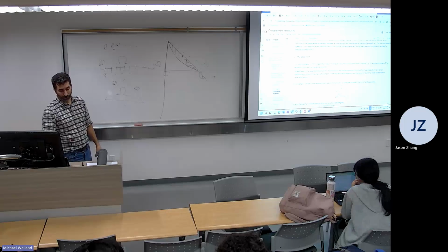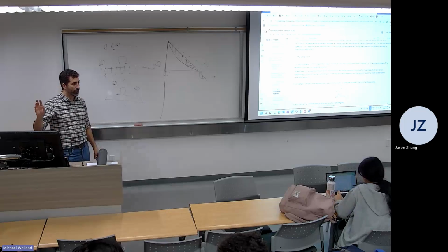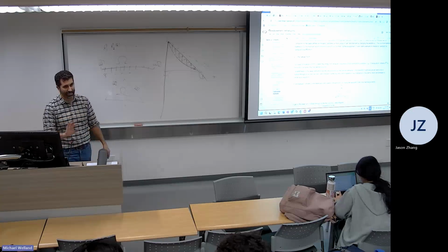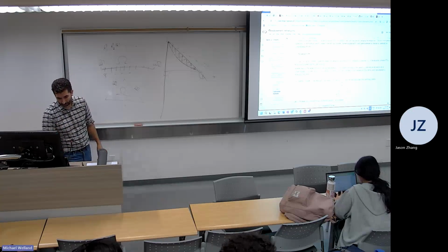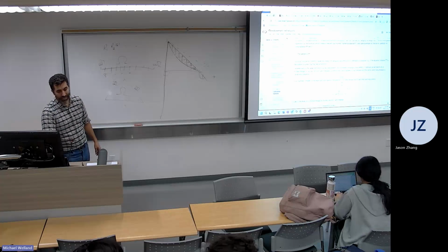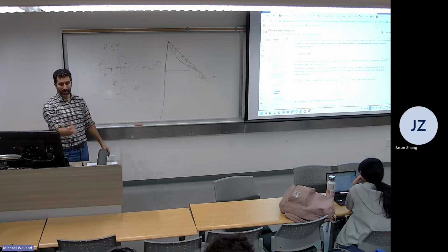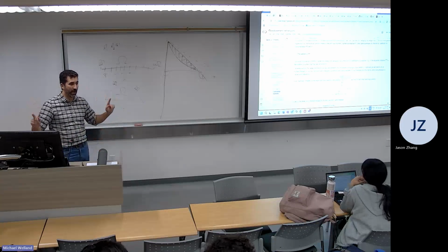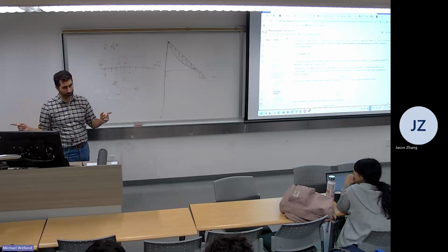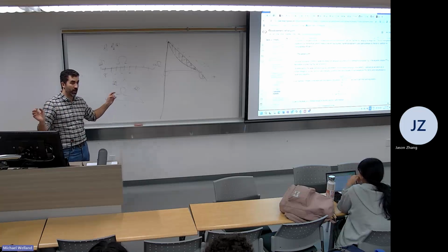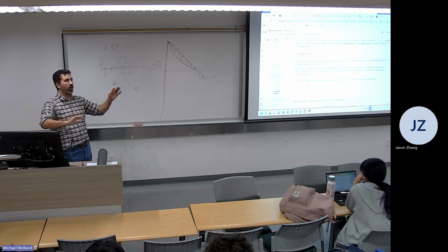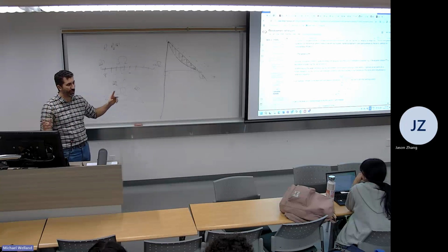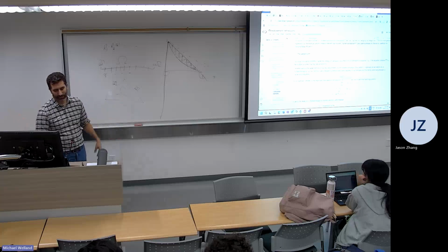MWR leads to the weak form because we're introducing this test function, but we can also just introduce the test function and manipulate things around, and we don't have a problem with it. What we have to do is we take our strong form, we multiply it through by this test function, and then we integrate the entire thing. And the magic happens with divergence of flux terms. And divergence of flux terms are prevalent, they're pervasive. Almost all branches of physics have some kind of divergence of flux because that's literally stuff coming out minus stuff going in is the rate of change of stuff. It doesn't get simpler than that.